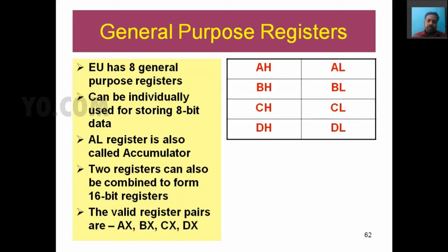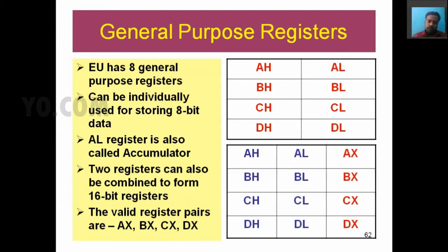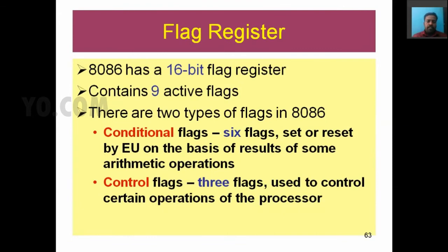It is divided into two 8-bit registers, that is AL and AH. Okay, so these are general purpose registers. AH plus AL equal to AX. X represents a 16-bit register. L and H represent lower and higher, that is an 8-bit register. Okay, right. Next, flag register.